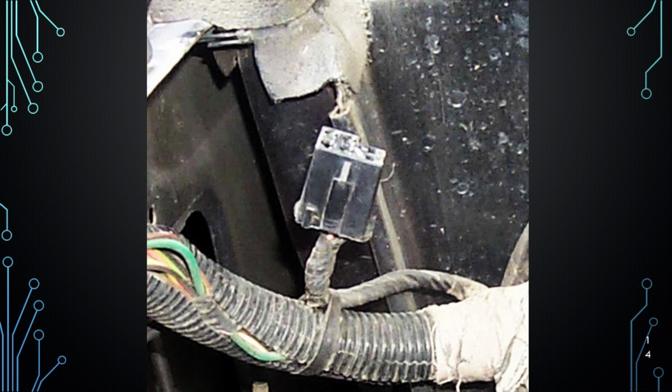That connector looks like a diagnostic connector from the OBD1 era, likely from a GM or similar manufacturer. It was used to connect a scan tool or jumper to retrieve trouble codes. By shorting specific terminals, the system would flash codes on the dash or provide data to a scan tool. It predates OBD2 and allowed technicians to read early electronic engine control data.